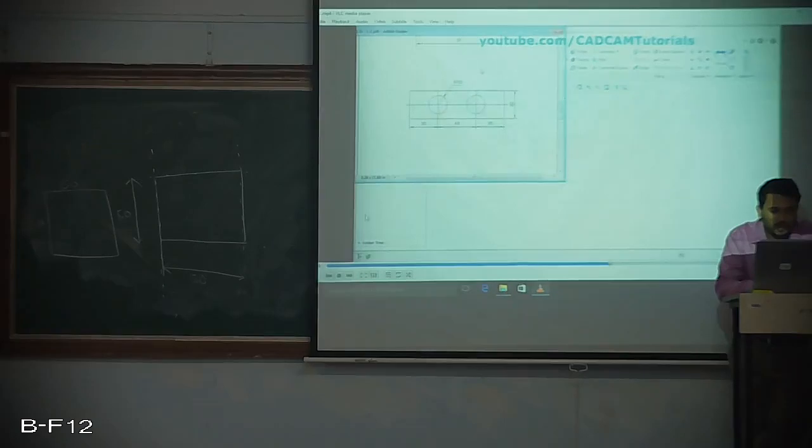So what I can do is directly use the rectangle command. I can draw this, and then place two center lines over here, and this distance I can place. I'll draw one more center line, a horizontal center line, and from here to here I'll place it as 15. Whenever I draw this I'll get two intersection points, so I'll take these as centers. I can draw the circle and then later change the dimension of the circle.